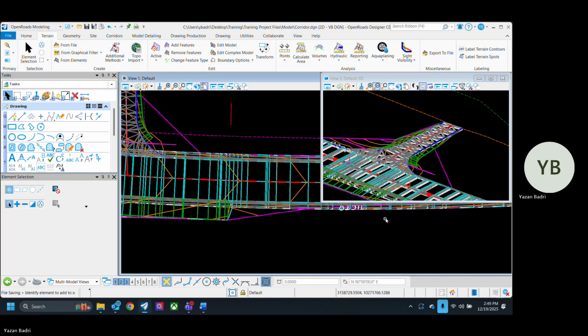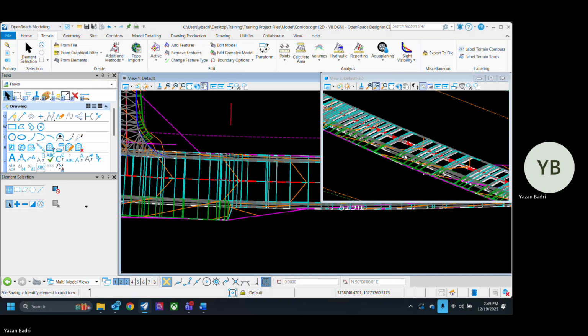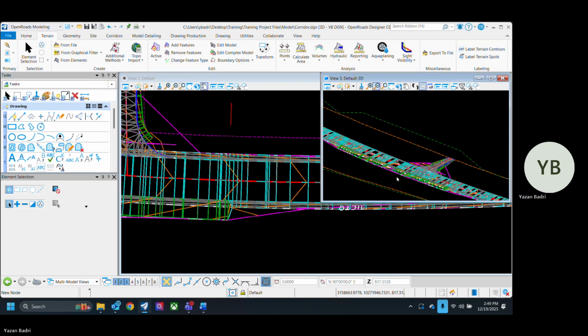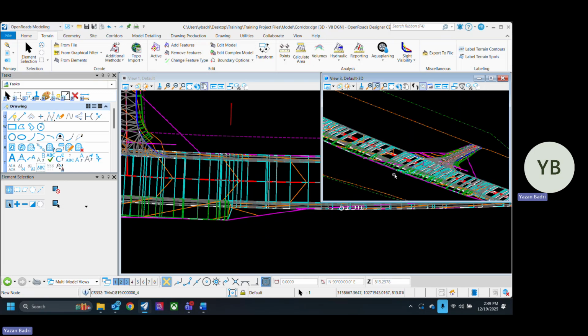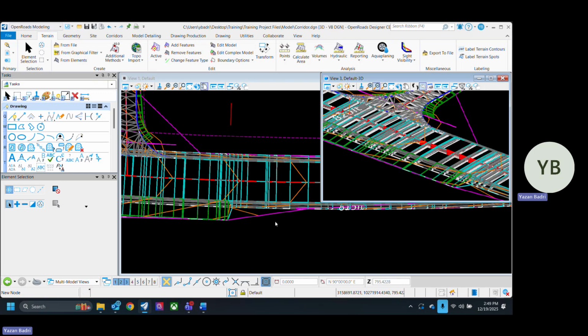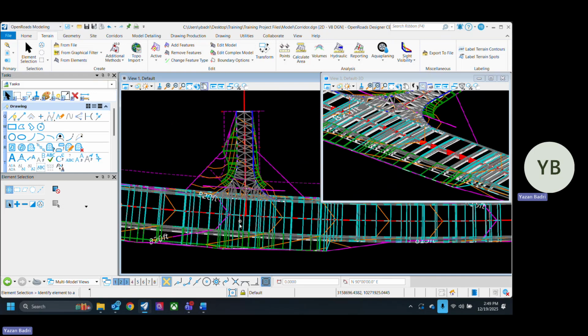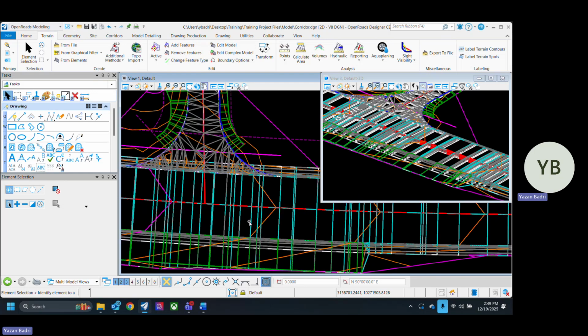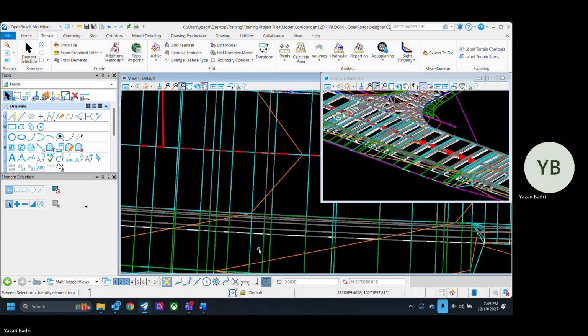Okay. Do you just make contours? What do you mean? You made a surface that was closer together. Oh, just turn on the contours? No, I mean, you turn something from false to true. Yeah, the top mesh. So we can see it, I guess. It's really more for selecting, because if I were not to turn that on, I have to select the pavement top mesh, and then I have to select the ditch. Every section separately. I can show you.